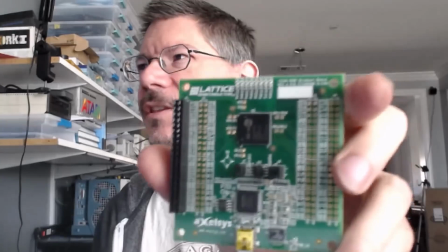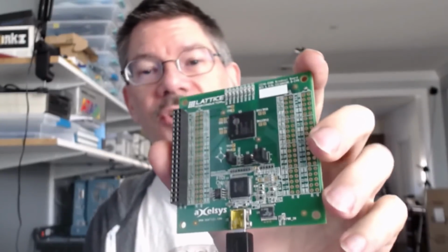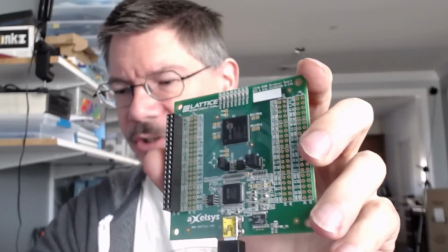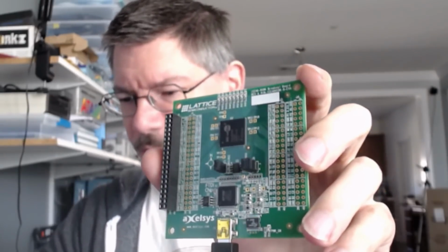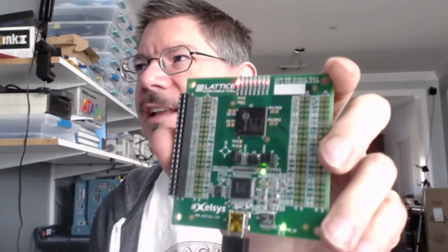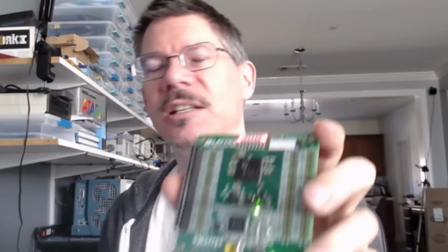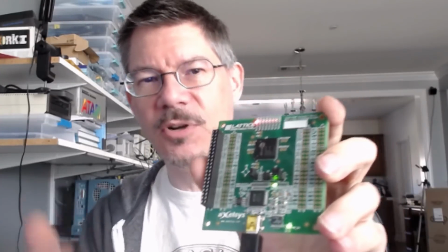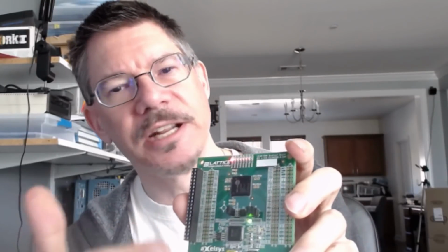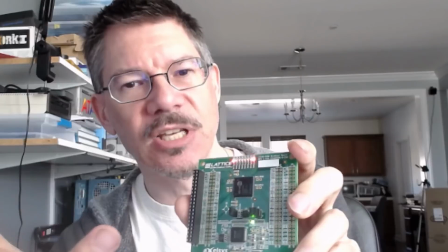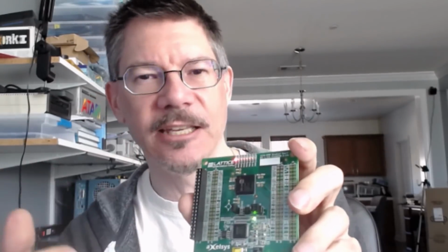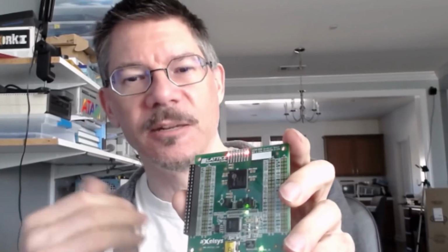Okay, now I've got the board unplugged, and just to show that we have actually put the program in Flash, so we don't have to reprogram it again, which would be kind of a pain, let's go ahead and plug it in, and we can see that our LED flashes again. So basically what happened is the program on FPGAs is stored in Flash, and then every time the FPGA starts up, the program gets loaded from Flash into all of the FPGA lookup tables and flip-flops, and then it begins.